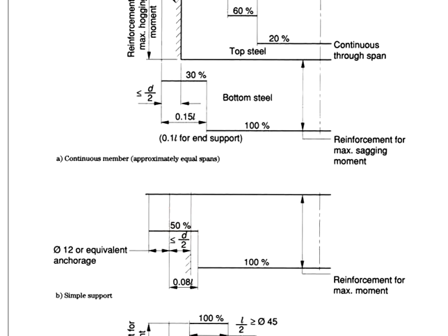Now the question here is where you can start curtailing your reinforcement. We are looking at a distance of 0.08 times the effective span. In accordance with the British Standard, this 0.08L shall be determined on the basis of half of the bearing area of the support. And then it specifies an additional 12 times the bar diameter or equivalent anchorage length to ensure the reinforcement is fully anchored inside the support.